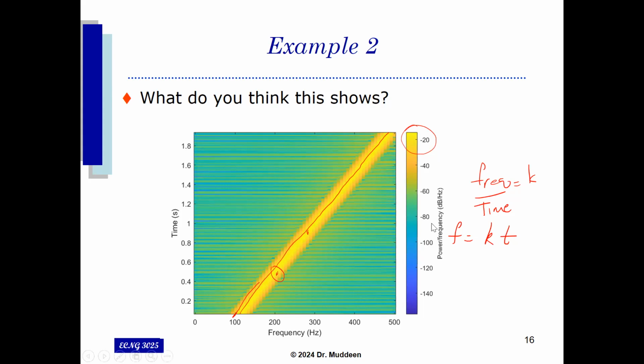All right. There are some other examples that will come up in the problem sets and so on. So to handle non-stationary signals, we need to take the signal and divide it up into smaller chunks. For each of the chunks, we do a spectrum analysis, and we put the series of spectra together to form an image called a spectrogram.